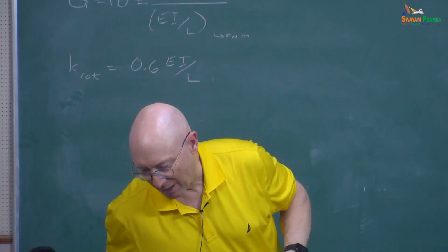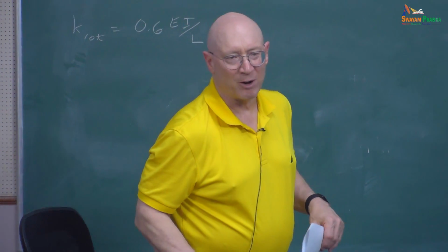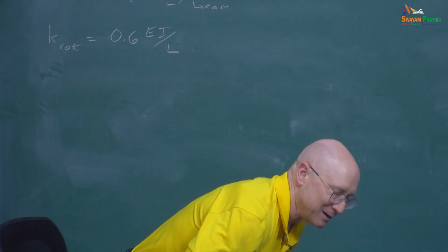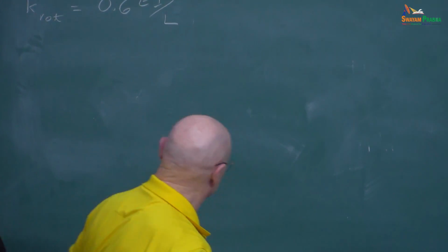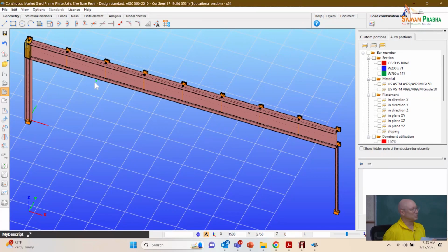And so this is a kind of a silly little way of saying, okay, let's count on some restraint. If you start modeling more directly what's really going on in a base detail, you typically find that this is probably a very small number at low load, but then at some point the simple base detail starts rotating a lot. It's a nonlinear response, but we're trying to do this without getting into modeling a nonlinear base response on the frame.